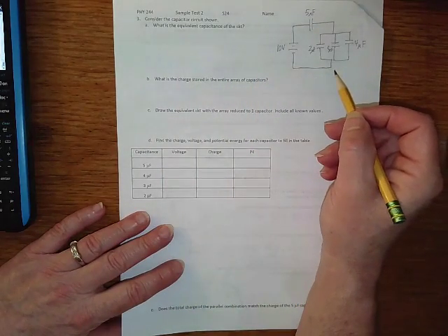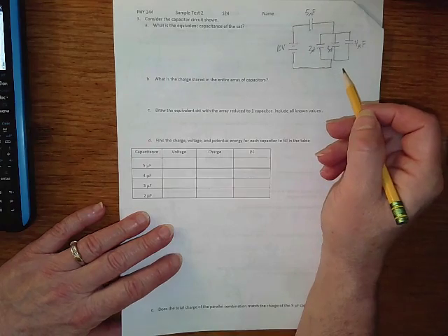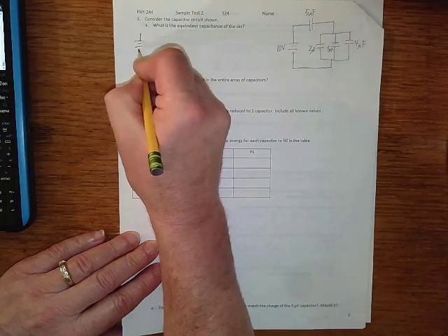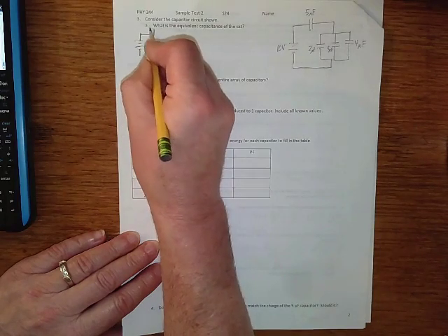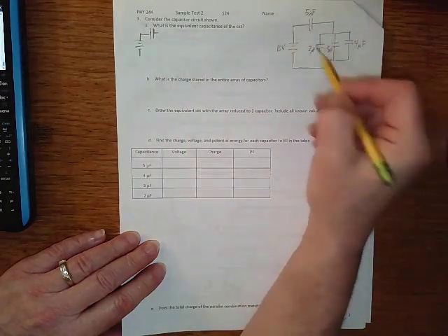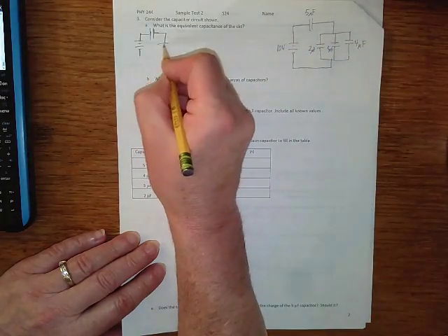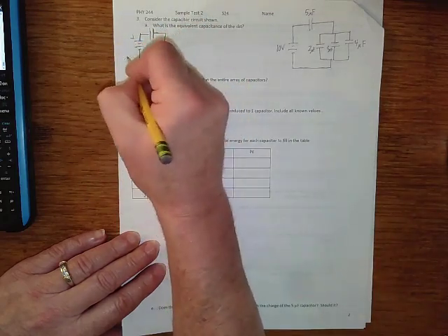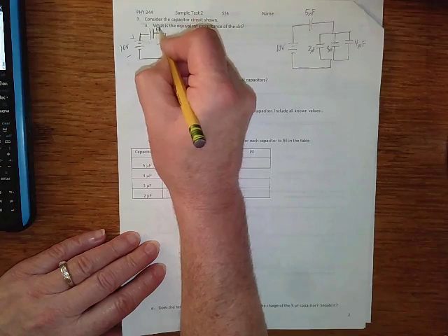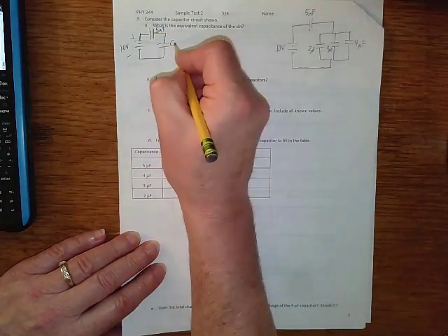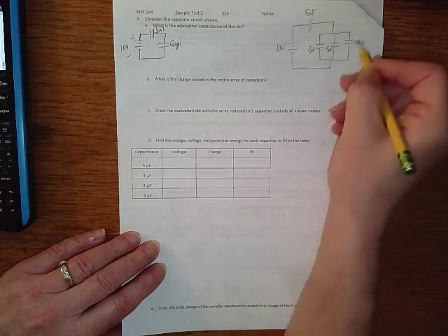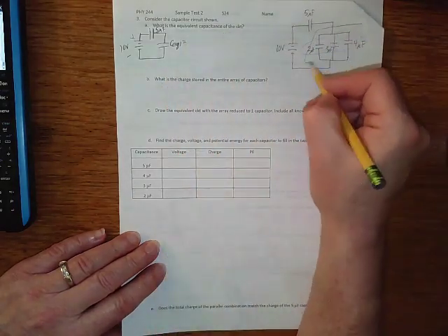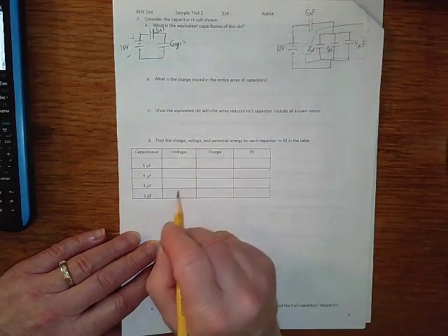So let's go ahead and draw an intermediate circuit just so we can remember. Looking at the circuit, hopefully it's obvious that these are all in parallel. If we make those into one equivalent, the source will stay the same, the 5 microfarad capacitor stays the same, but now we're going to have some sort of C equivalent 1 here, which is going to be 3 capacitors in parallel. These 3 are going to be mushed into one C equivalent to start with.